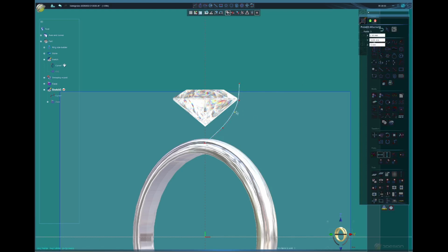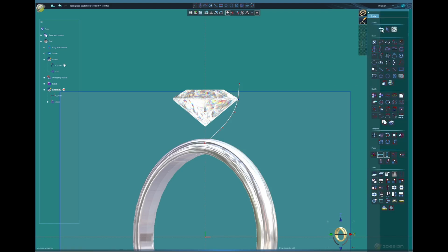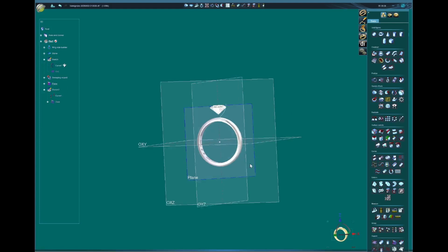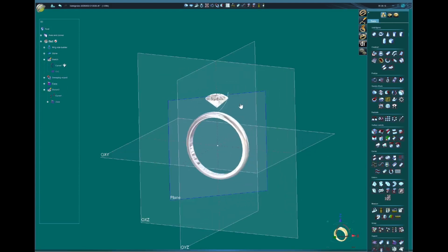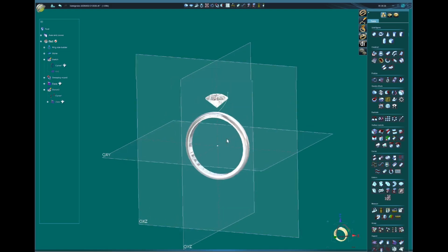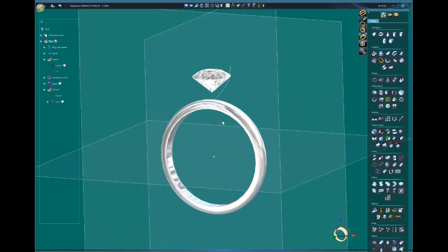Let's just bring a little bit because it's kind of weird. So let's click OK. Leave the sketch area. We can also hide this plane. You don't need that for now. To hide, you just press your space bar once and it's going to hide for you.